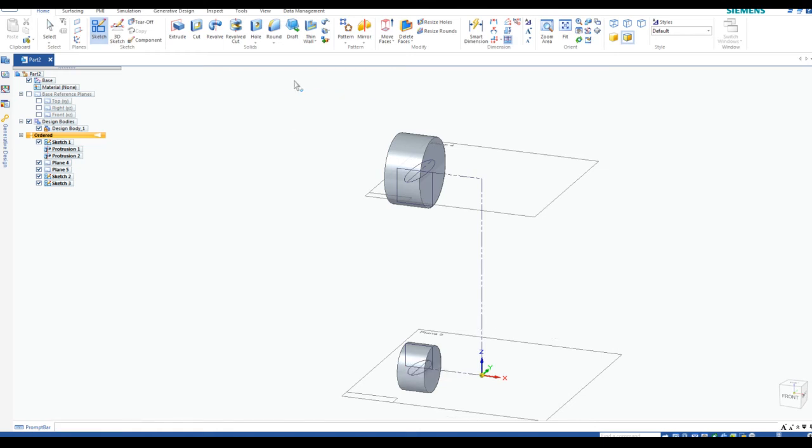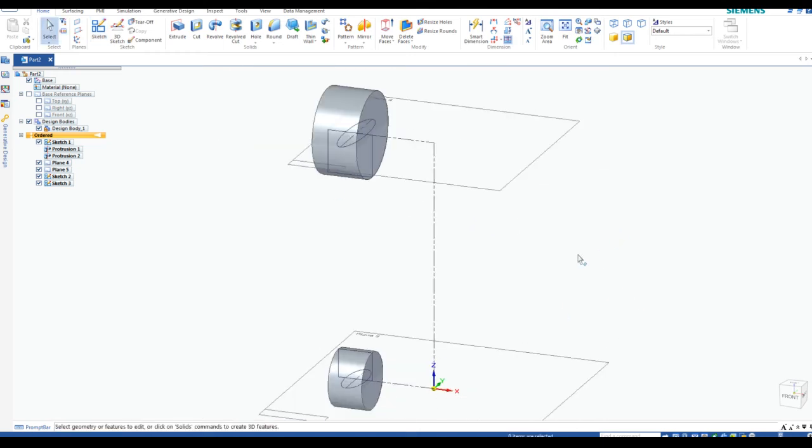And we're going to finish all the commands. Now, remember what I said. A lot of times when we add geometry or objects to our drawing, it tends to become cluttered. We don't necessarily need to see these two work planes at this point. So if we go to our history tree and we take the check mark off, it'll turn those off. Okay? Also, sketch 1, we'll leave it as is, but make sure that for our next step, we're going to select the ellipses, not the rectangles.